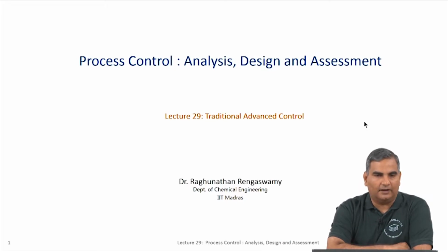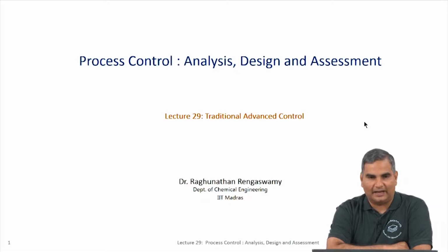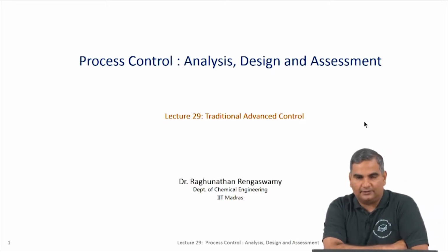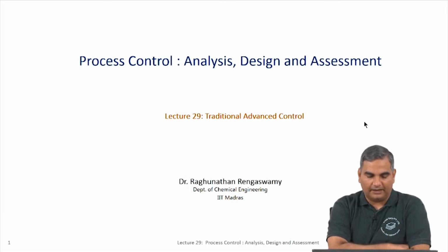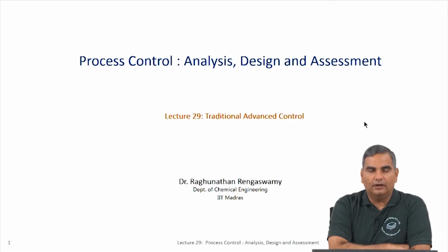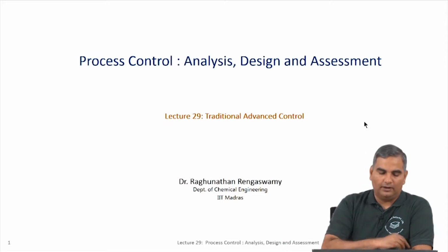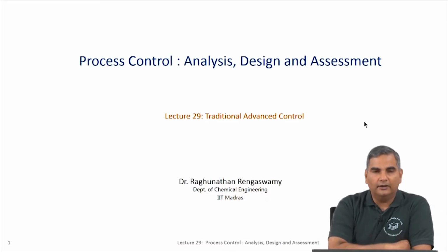And then I talked about adding some structure to this closed loop in terms of a cascade control. I explained a physical system where we might need to use cascade control, and then explained how you could modify the closed loop system by including a measurement and making hardware changes, which allows one to come up with two loops within this closed loop diagram, one inner loop, one outer loop. I also showed how you can simplify the inner loop and come up with one block diagram which includes both the inner loop and outer loop in a form that we have seen before, so that we can go ahead and do all the analysis that we have learned from this course.